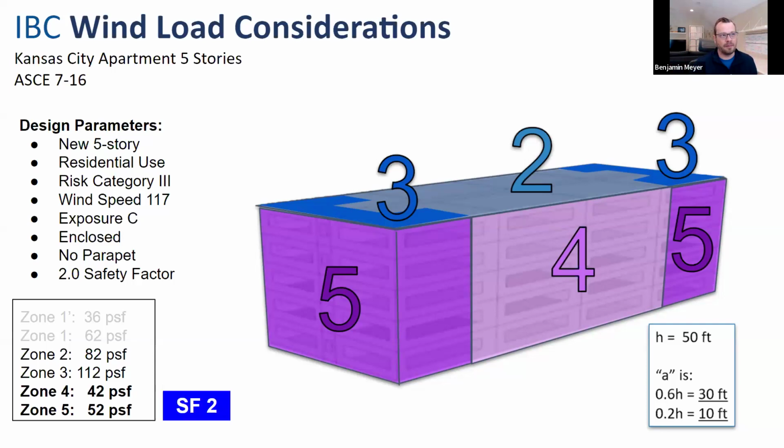You know, when I was in consulting, many times we would have locked in roof performance, and then we would say, well, if we just use a cheaper window, we can save a whole bunch of money. Is that okay? Well, the cheaper window doesn't meet the performance requirements in many cases. There's a reason it costs less, but we're not applying the same level of rigor to it. Yeah, value engineering rarely takes a holistic look at the entire building.